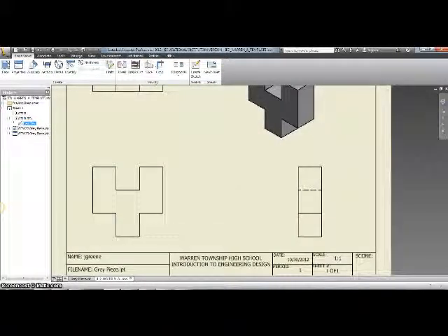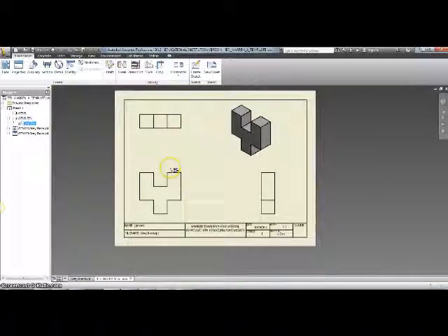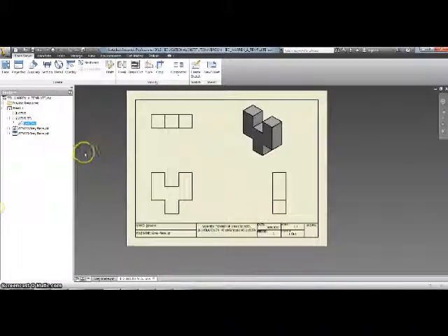Now finally, we have 4 more puzzle pieces to complete. To do this, we need to create more sheets on the left-hand side. We should never ever use more than one file to create multi-views. We should only use one file and create multiple sheets in one file. So to do that, on the ribbon, we can go to something called New Sheet.